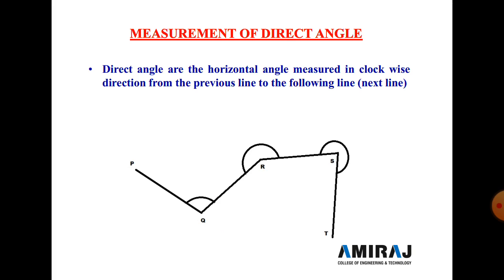And in window A, set the reading 0 degree in a horizontal plate. Clear? Then after the upper clamp is perfectly fixed, we set the 0 degree at the Q point, and then after bisecting the P point ranging rod here, fix the lower clamp screw.